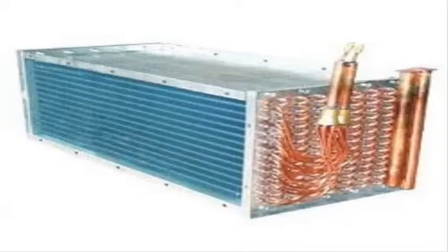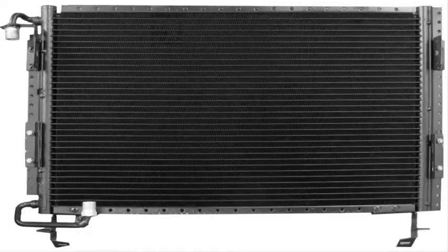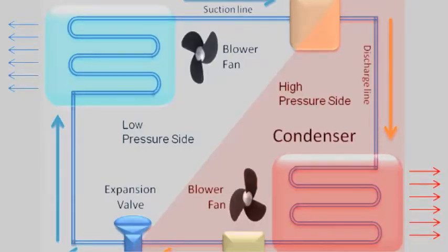It just transfers heat. For heat to transfer, there has to be a temperature and pressure difference. In the refrigeration process there are two sections which produce a pressure difference: a high pressure, high temperature section, the condenser, and a low pressure, low temperature section, the evaporator. The refrigeration system removes heat from an area that is low pressure, low temperature, normally called the evaporator, into an area of high pressure, high temperature, normally called the condenser.